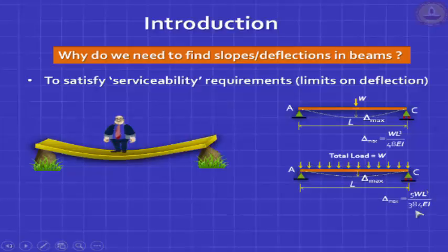And it's nice to compare with this, so we must put both in with the same denominator. 1 by 48 also turns out to be 8 by 384, and if you compare the concentrated load case with the distributed load case, you notice that the ratio of this deflection to this deflection is 8:5. In other words, 60% more than had the load been uniformly distributed.